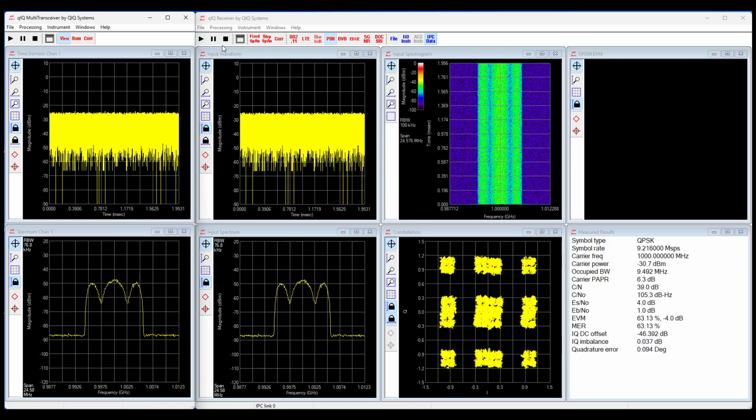And if we stop this, and you look at the frequencies that we're dealing with, remember 1 gigahertz is our center frequency, and this is about 2.5 megahertz to the positive side. This is about 2.5 megahertz to the low side. That's a 5 megahertz separation, and you take 1 over 5 megahertz, and that's 200 nanoseconds. So the 200 nanoseconds of delay that our multipath signal is coming in later begins to create this interesting character in what used to be a flat top spectrum here.